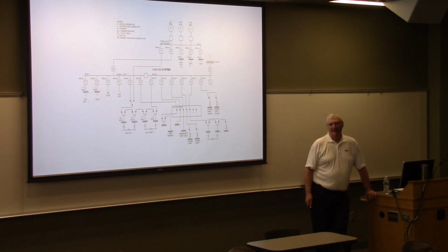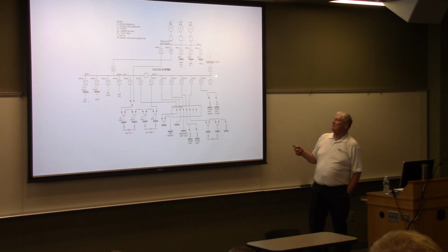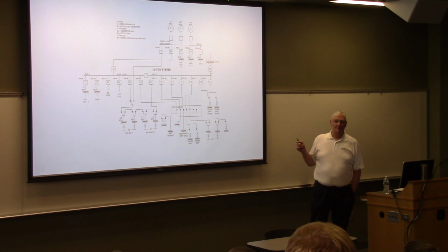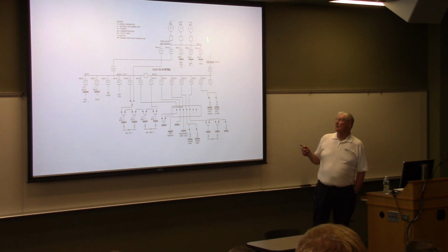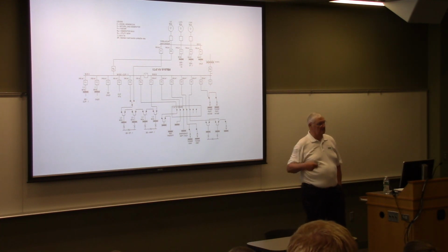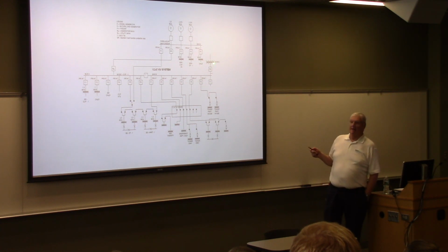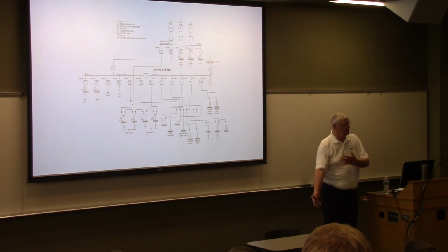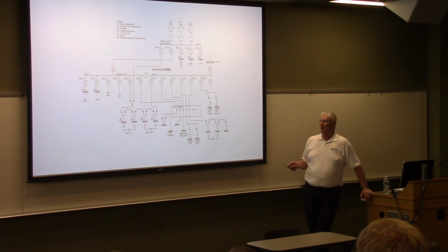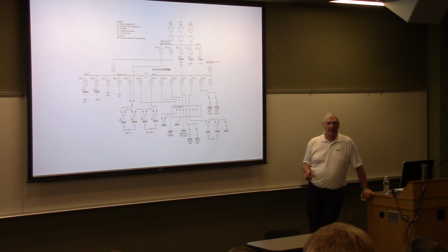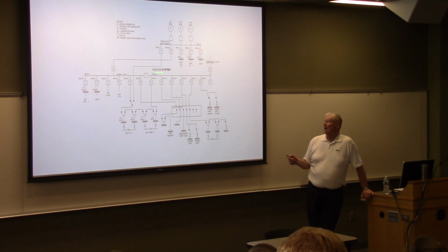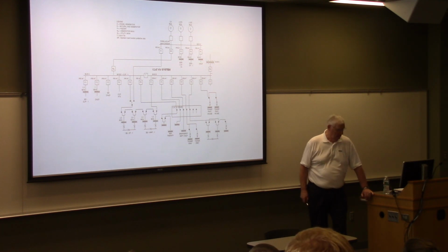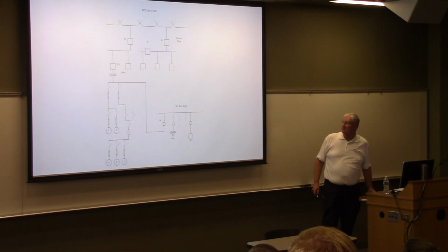systematic in this. Come to find out that the utility company was going to service this distribution feeder from the substation. So they took this feeder and put it on a different substation that wasn't as strong as the original one. And what they did in the mornings, because it's summertime, they put capacitive kVAR correction on here, which caused the relaying here to see an overvoltage, which caused it to disconnect and go through this emergency operation. So with all the good intention of all the settings that we worked out in the original design and whatnot, we had to come back and increase the overvoltage trip points on this relay and this one here so that we could accommodate this particular requirement. You're not always done when the system goes in.